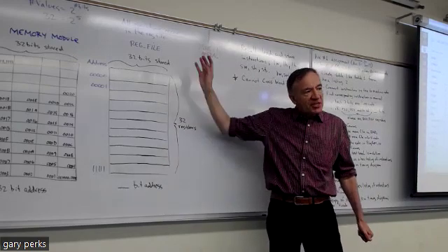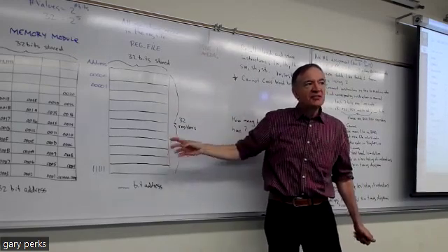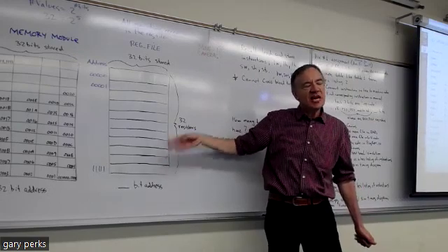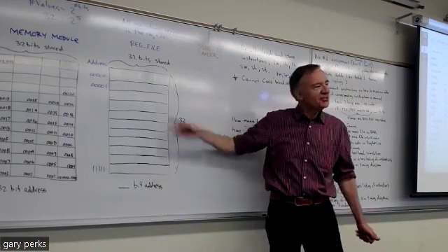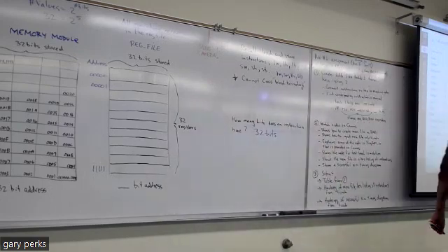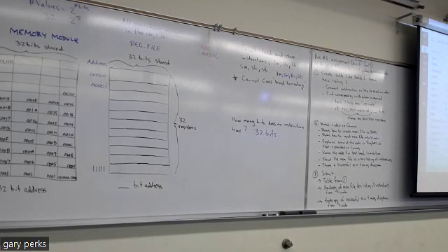Okay, and how many registers are in the reg file again? 32. And how many address bits do we need to address 32 registers? 5. So look, this command has RD, RS1, and then when you look at the machine code, see right here, RD, 1, 2, 3, 4, 5, 5 bits. The reason it's 5 bits is because the address of whatever register you're using to put the result in would go there. So let's say, once you convert those hexes into binary, there's a binary 10 here, that means your destination register is register 10.